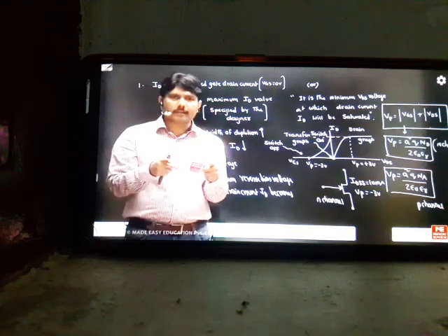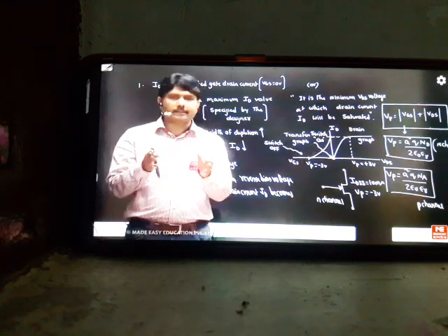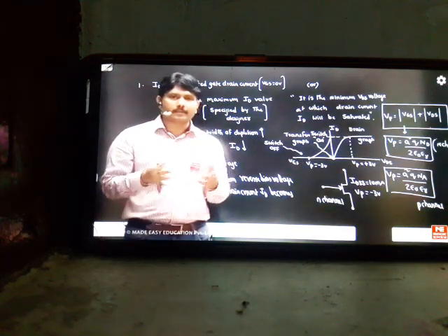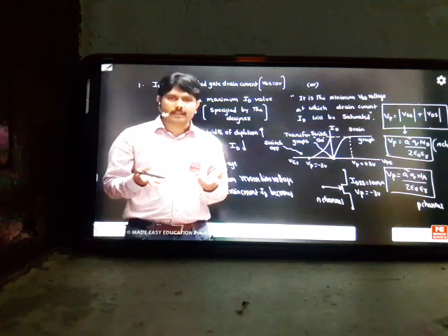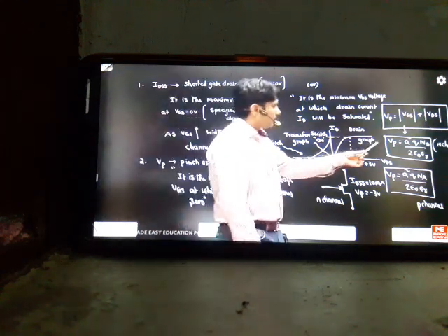If you take Nd, it is an N channel, the donor concentration. For a P channel, it is Na. It is entirely depending on the channel doping. That is the reason these values we should not calculate. The doping, how much the designer added, he knows; I don't know. That's why these formulas will help you to solve certain 1 mark questions for you.